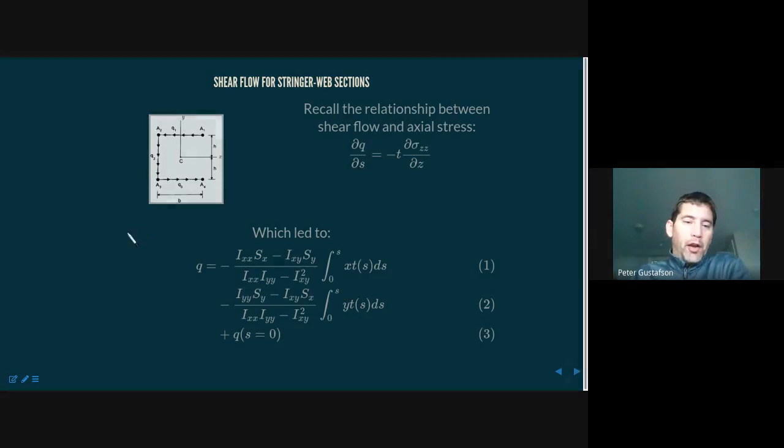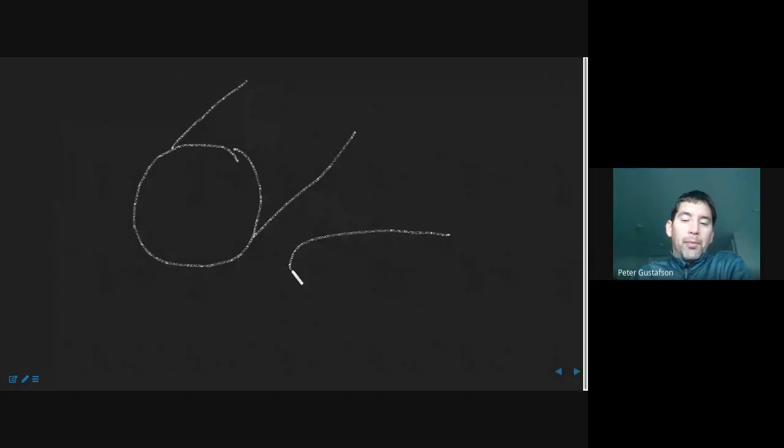So closed cells we had initially drawn, we started with something like a circular thin-walled beam structure that was carrying a torsion load. And the next and last thing that we did then was multi-celled structures. So the classic example is probably the airfoil structure. That then is divided, has a leading edge and a trailing edge spar. So now we have three cells. And so we talked about how to do those, and we did closed cells and open cells.